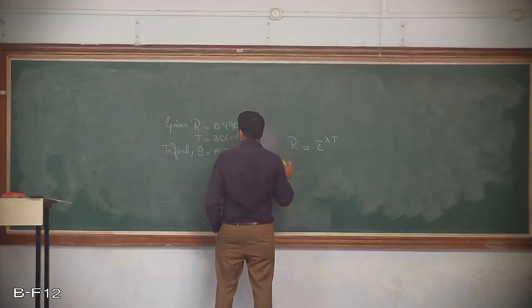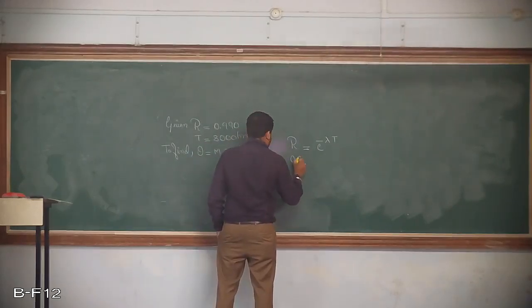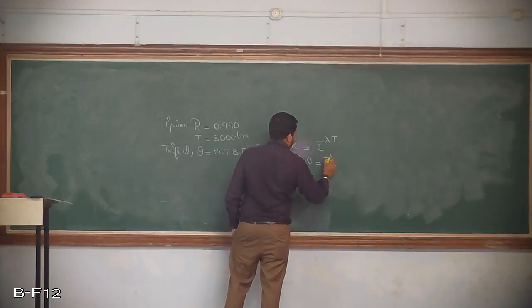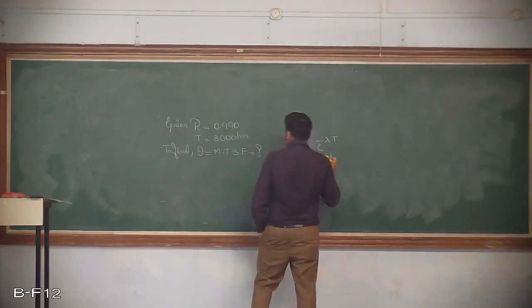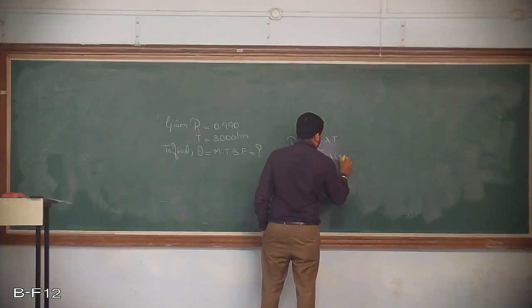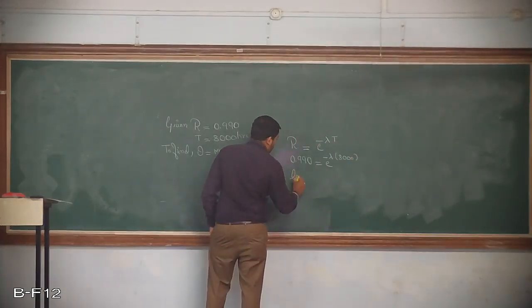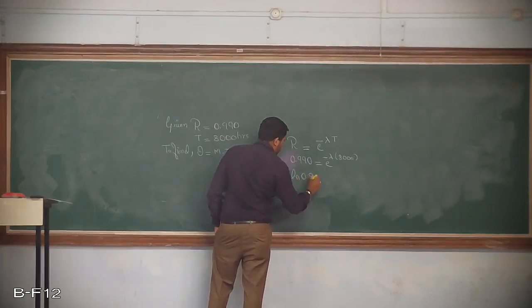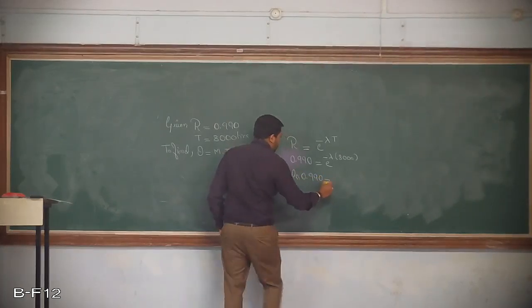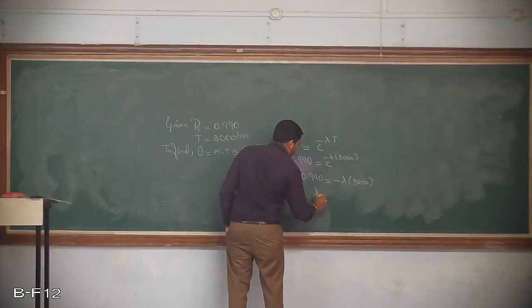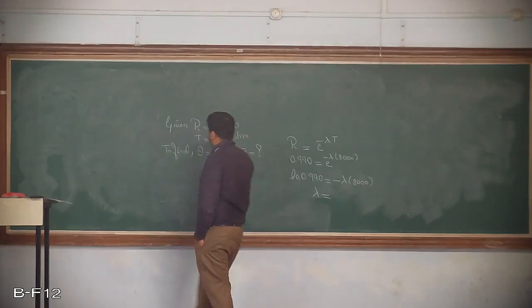The reliability is 0.990, e raised to minus lambda, which we don't know, t is given as 8,000 hours. So just find out the value of lambda.